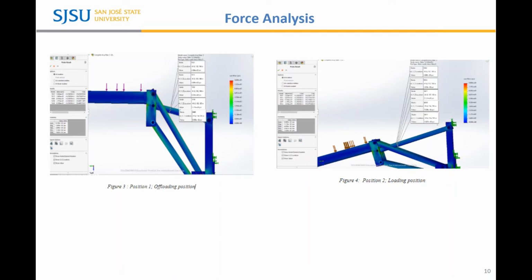A similar process was conducted to find the correct winch size for our design. To select the correct size for the winch, a bar was positioned as a placeholder in SOLIDWORKS simulation. The bar has multiple probes attached to it as shown in Figure 3 and Figure 4. This placeholder was then used to evaluate the forces that will eventually be placed on the winch by dividing the stress by the cross-sectional area. A distributed force of 1,000 pounds was placed on top of the ramp.